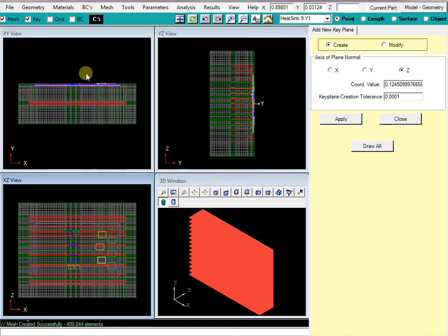Normally you would know the application, and maybe you have some radiation coming out the base here, or maybe you have a convection air coming over it, or there's an enclosure box on the back here. But just for this, we're just going to leave it. And majority of the heat, obviously, we have this metal PCB. 95 to 99% of the heat is all going to be coming through that board and going out these fins.